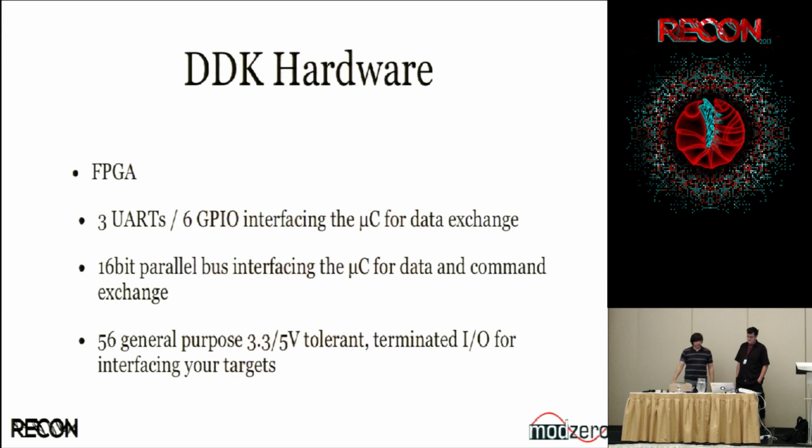Okay, but so we also have the FPGA. In terms of us thinking about you trying to do custom things on it, we chose our pins carefully. The other thing which can go terribly wrong if you're designing your own board is you'll basically have the worst combinations of signals ever connecting two chips on your board. So in this case, we spent the time to think about what somebody who wants to do something completely custom with this board will want. And the answer is they want UART. Believe me, because UART's the easiest thing.